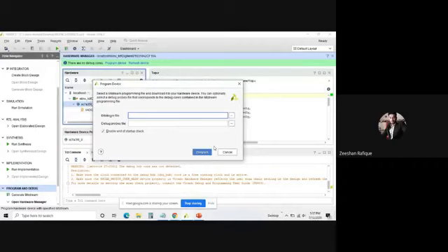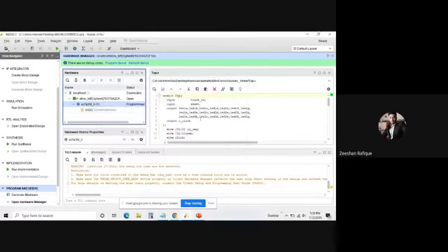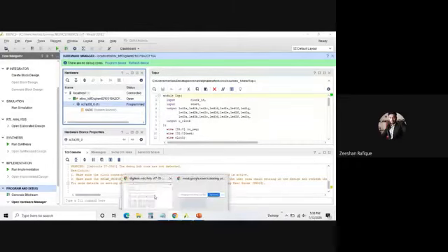Okay, let me clear the thing. What is the bitstream file? Bitstream file is the file of zeros and ones which reconfigure your FPGA board according to your code you have written. So once you upload this bitstream file on FPGA board, you can see this video. Let me show you.